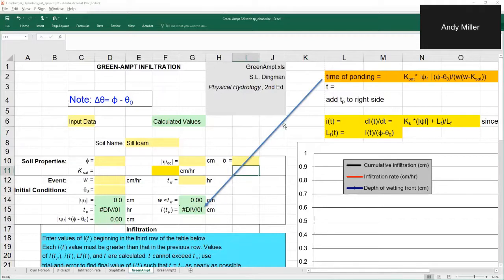Similarly, they give you, actually, I had a whole recording that I developed using this spreadsheet, and I used it in the earlier class. We don't have time to listen to it right now, so I'll talk about this a little bit on Monday. But I'm just going to show you some things that are in here. So saturated hydraulic conductivity, you can give it a value in centimeters per hour, and then you'll be doing calculations based on centimeters per hour.